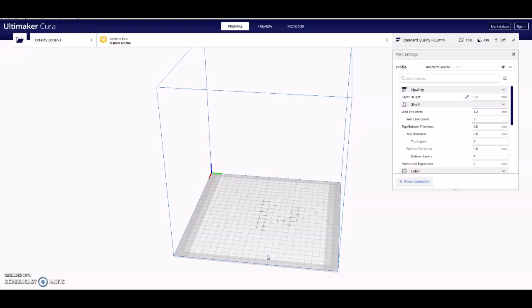If you're going to print on the white ones in my class, you would use Cube Pro software. If you're going to print on the other ones on the other side, the Airwolfs, you would use Apex software. This one we're going to use Cura. It's an open source software, and it actually is for a bunch of different printers. You just have to click and add the printer you have, so it adjusts all the inside settings of the software, so it's ready for this one. This is a very popular printer because it's so cheap and prints so good. It's very popular, and definitely it's in here, so you have to add the printer.